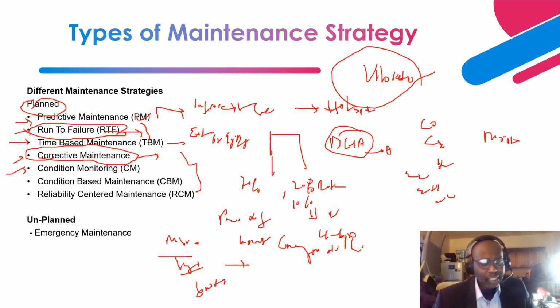Next is condition monitoring. I gave you similar examples, where for a power transformer, you can have a bushing monitoring device mounted at the top of the bushing that collects and spits out real-time data on the bushing capacitance, C1, C2 section, tan delta, leakage current, and the voltage and the current that flows through the bushing.